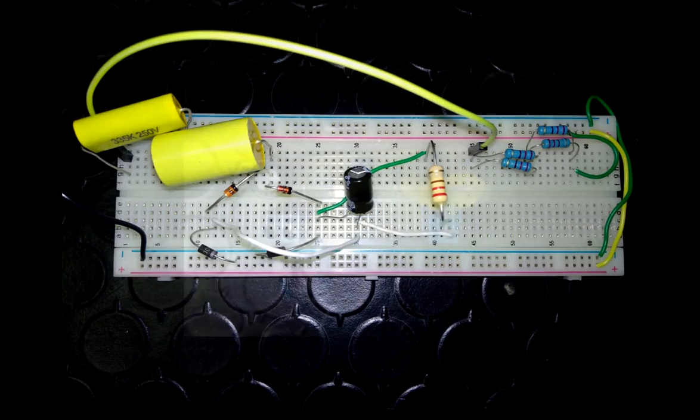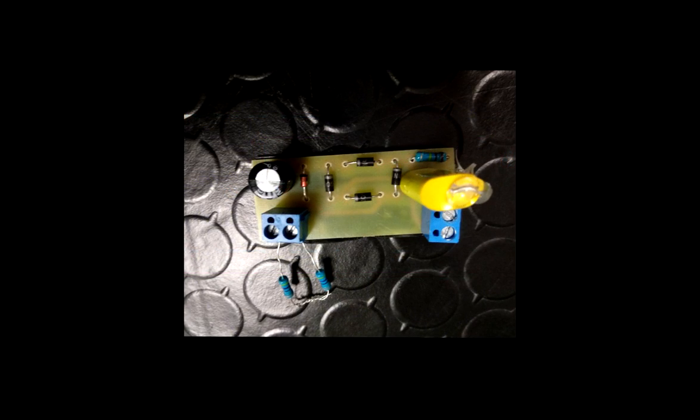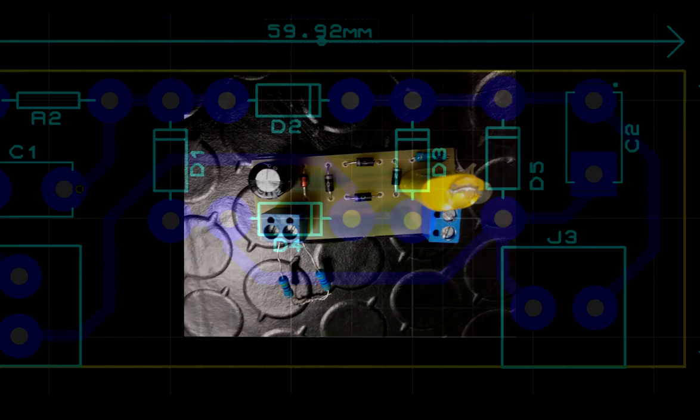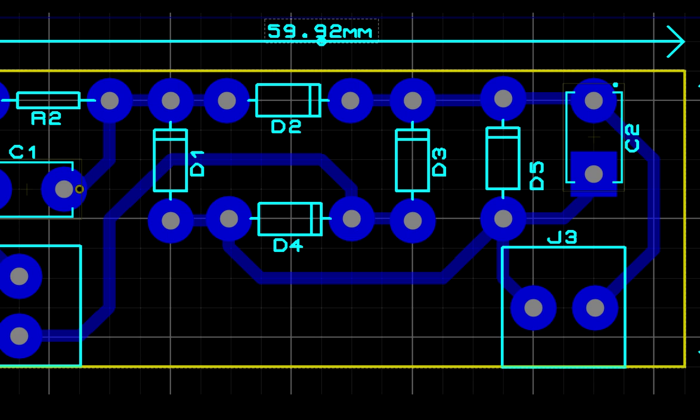Then, to get more realistic output values, the team welded the elements over the PCB, taking care not to damage the board and also to secure that the connections don't touch each other. The final dimensions of the PCB were 6 cm wide and 2.5 cm high. Two blocks of connections were added to make the output test comfortable and easy to change the output resistance values.